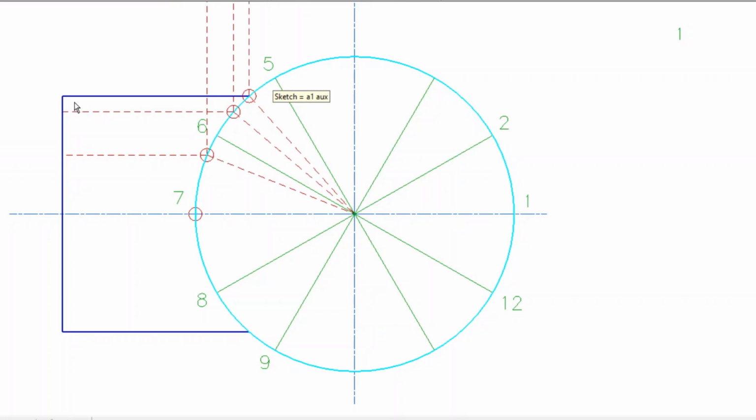Remember, the same penetration points we use for the branch, we have to use for the main as well. So we're going to have 2 points between 5 and 6, and then 1 between 6 and 7. We're not actually going to use 5 and 6 as penetration points, only 7, because remember the center also acted as a line of penetration. So 5 and 6 will not be penetration points, only the points in between, and that is the main difference between the grade 11 and 12 one.